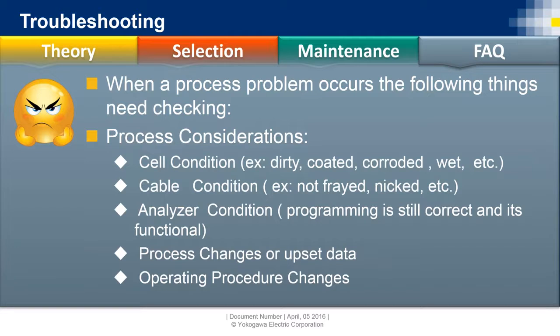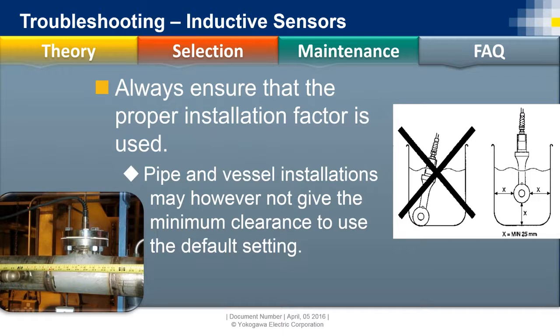Other times, what we'll look at is obviously process changes. This is when we have problems where I just stuck this in and it only lasted a week. Why did a metal sensor just last a week in a process? If it was something that wasn't a high temp sensor that had high temps, put in the boiler drum, steam drum, the O-rings fail, the epoxy sealing inside the sensor is not meant for high temp, those will fail. So we look at that kind of stuff.